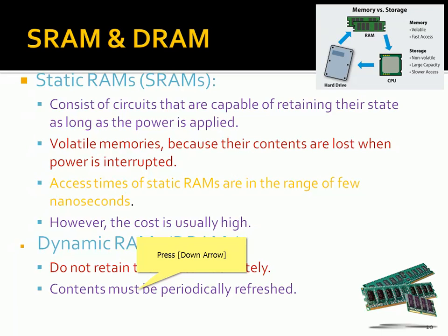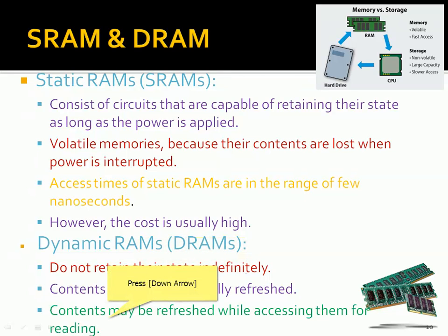Based on that cell, a refreshing circuit is essential. Why does it need to be refreshed? The data may be lost. After some nanoseconds the data is going to be lost, so before that time we need to refresh it. Refreshing means we need to supply power, so it regenerates and recollects the data. Otherwise the data will be permanently lost. That kind of concept is imposed in the construction of the dynamic random access memory cell.